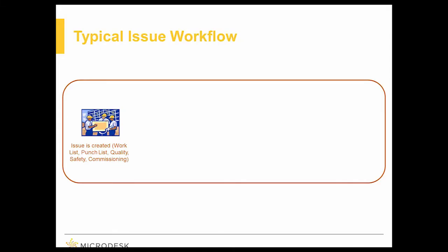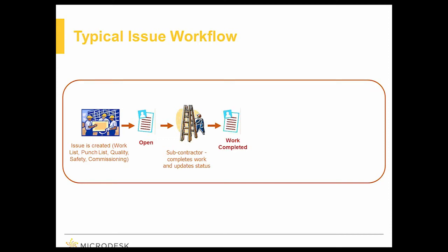Now, issue tracking comes into this because, again, we might have an issue or checklist, punch list, or for our friends over in the UK, a snag list. We might have things like that that we want to assign to different pieces of equipment. So, okay, we have an issue. We're going to open one up and we're going to assign it to that element. So it could be something like a subcontractor completes work, equipment arrives on site, equipment is damaged. It could be anything. So once we say that, okay, this has been done, typically somebody needs to go out and inspect that just to confirm that, yes, this has in fact been finished, this has been repaired, this is okay. And then from that, if it fails the inspection, that is left open. So somebody still has to go back and do that, and it's assigned and you can track that.